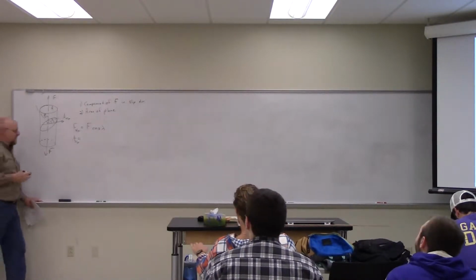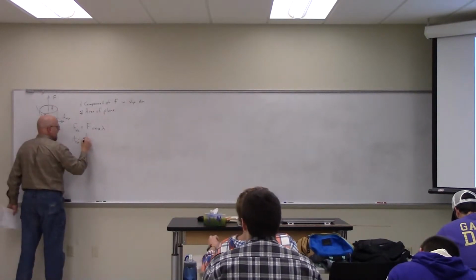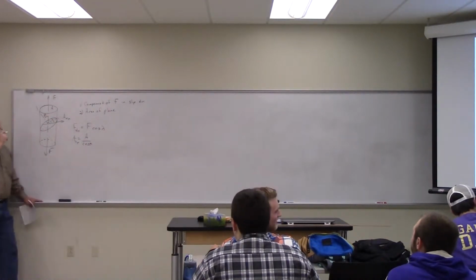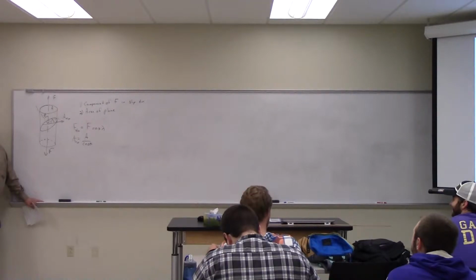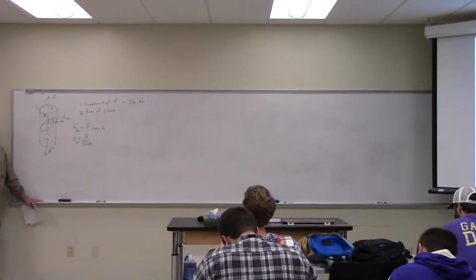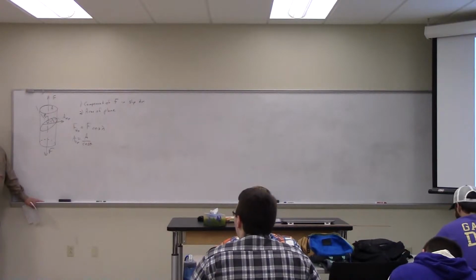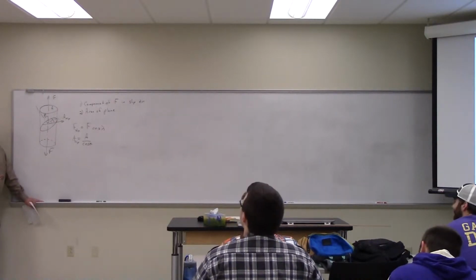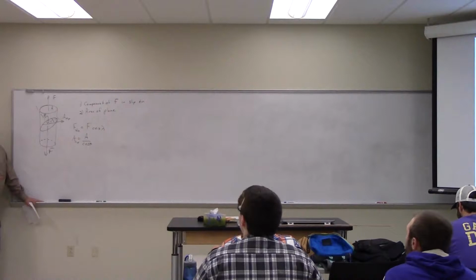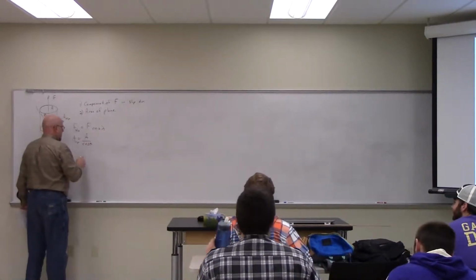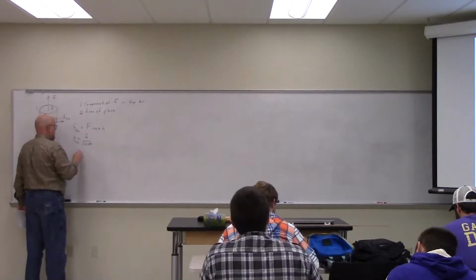The projected area is A divided by the cosine of theta. Because as theta goes to 90 degrees, that area becomes infinite, and when theta is 0, it's just A. Okay. So what is the stress on that plane then?